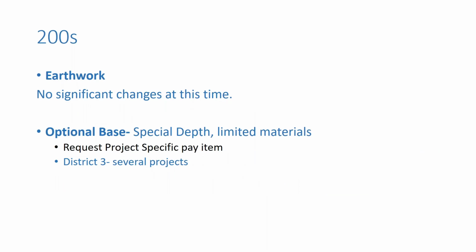In earthwork, there have been no significant changes recently. For optional base, we have had some requests for special depths for limited materials, specifically some of our graded aggregate base. So if you do have a need to have a special depth, please work with your district estimates office, and those requests are reviewed by the pavement design office and can be opened on a project specific basis.